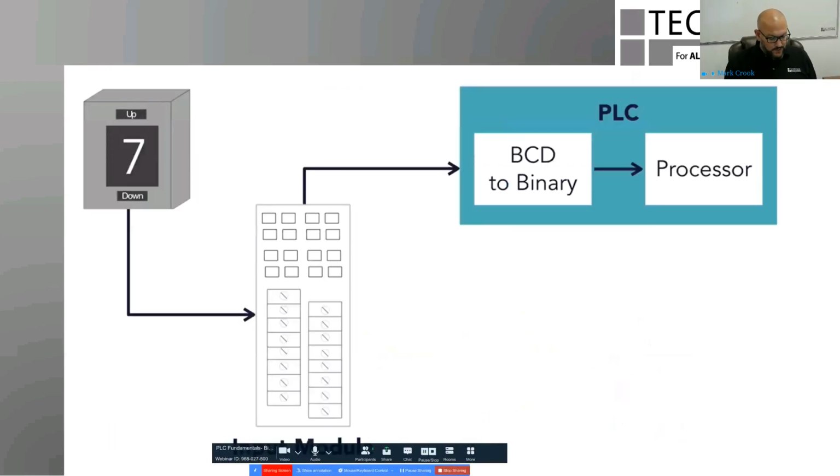So we're going to use the Thumbwheel. It's just one example of a device that could be used. The Thumbwheel has 4 output connections and a common output. Each of the 4 connections, the first, second, 4th and 8th, represent a binary weighing of that number, and they are individually wired to the PLC input. So for number 7, the PLC represents it as 0, 1, 1, 1, which is 1 plus 2 plus 4.